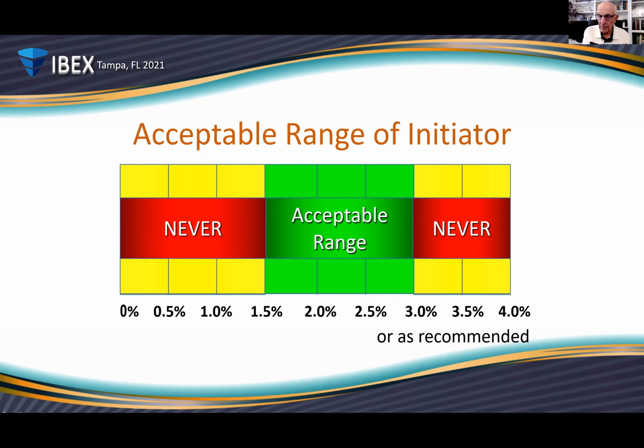Again, when I'm talking about that, I'm talking about reaching the ultimate hardness and the ultimate weatherability. So you want to be very careful about using those summer blend initiators. If you are using a summer blend initiator, rather than spraying at 1.5%, you have to spray at something like 2.8% to get enough active oxygen. So be very, very careful about that.